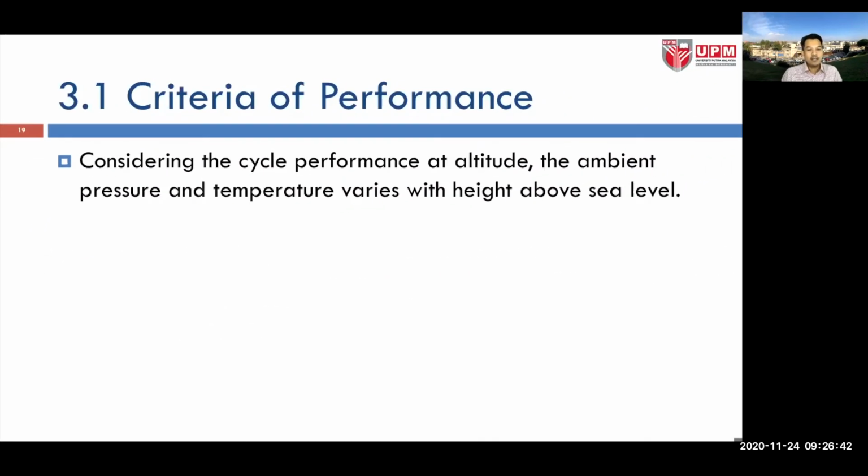So considering the cycle performance at altitude, the ambient pressure and the temperature vary with height above sea level.